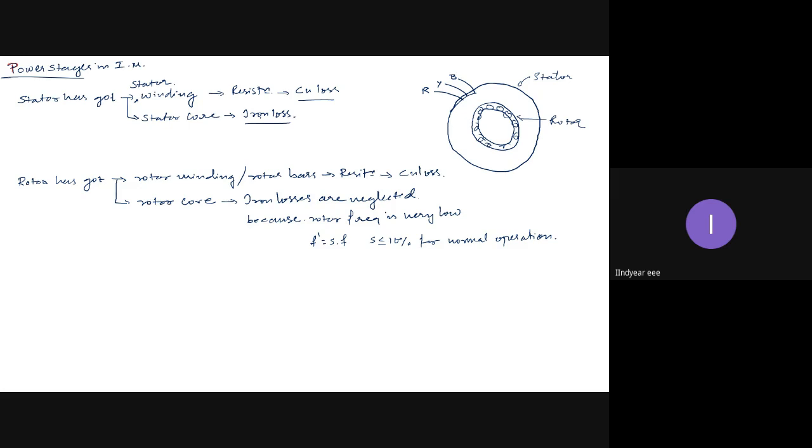Now, there is power available to the rotor to develop the mechanical power. So, all the power that is received from the stator after satisfying rotor copper loss, the power is developed in the rotor, and this is known as gross power developed in the rotor. It is exactly like the gross torque or gross power developed in the armature of the DC motor, PA.